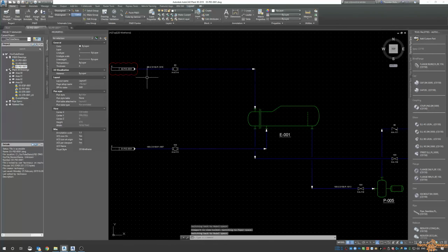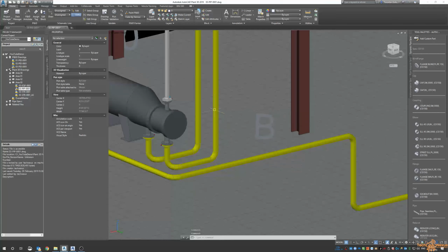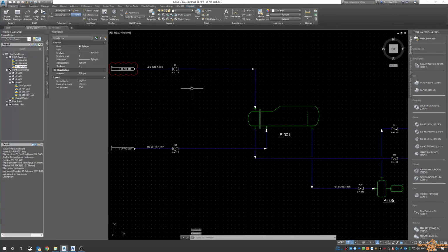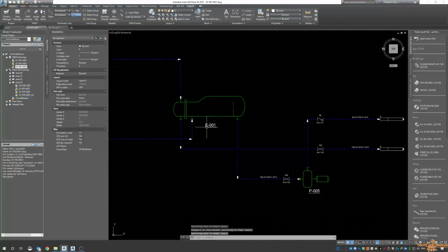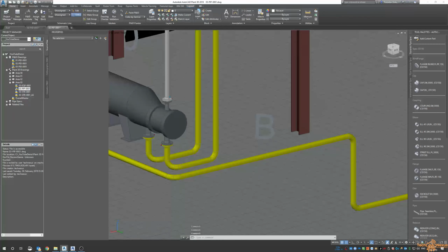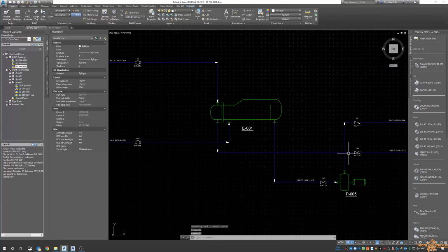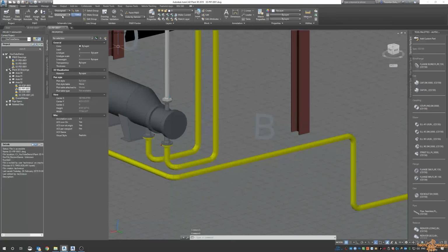For the other two runs, the line coming in and this line coming in, one from the top here, one from the bottom, both have ball valves on them as well. We don't have anything on the discharge. We've got a gate valve on the discharge side. Okay, so on the gate valve discharge on the head here, we're going to place, what was the spec? So it's a CS150.